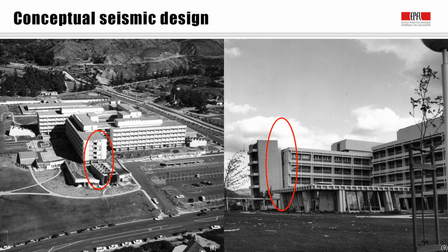An example of a building with a complex floor plan is the Olive View Hospital that was heavily damaged in the San Fernando earthquake in 1971. You can see here on the photo that the building consists of 4 wings that are connected to each other, and this really creates a dynamic response that is really difficult to predict. But the building had another problem.